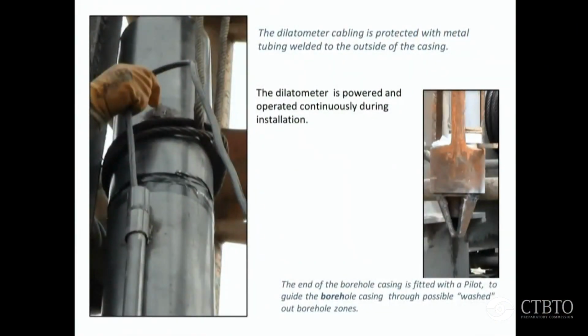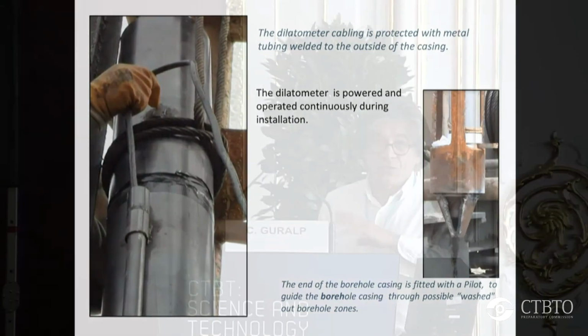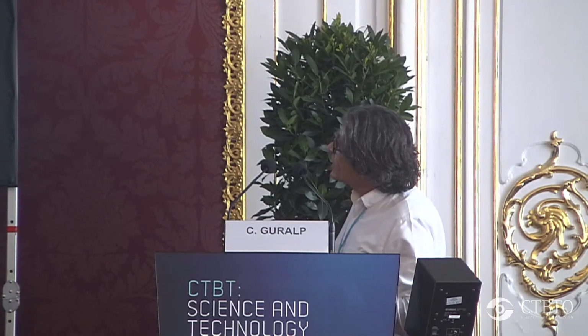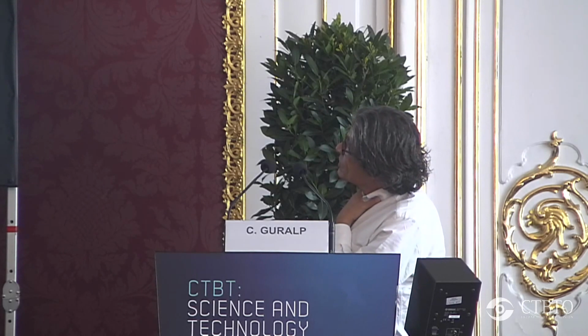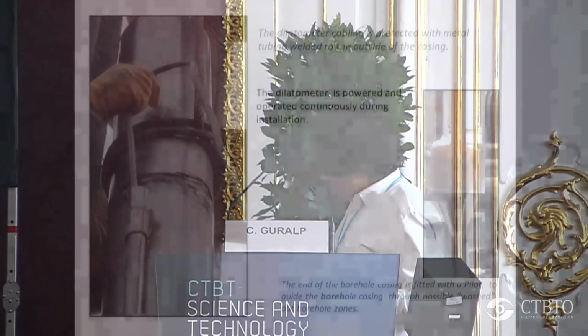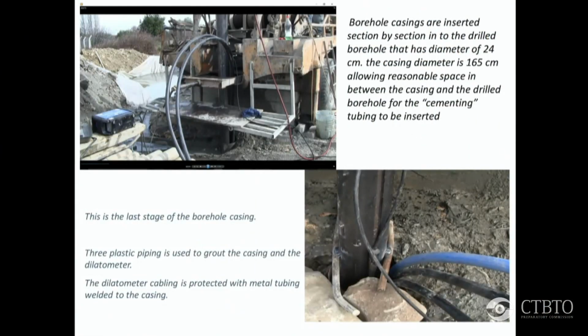In order to get the cables out, this is the practical side, which is very important, we had to put tubing on the outside where the dilatometer cable came out. More importantly, in order to understand that the dilatometer would work throughout, we actually operated the device as we installed it. And that took about, as I said, a day and a half. And of course, in order to penetrate into the formation, we had to have a reasonably strong end, but the dilatometer certainly survived. So that is the basis of the instrument.